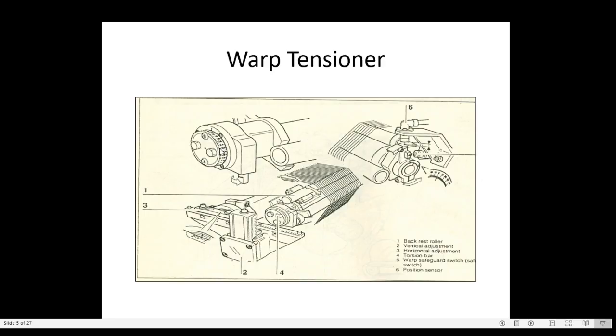When 5 kilonewton comes, we fix this nut. First we loosen this check nut, adjust to 5 kilonewton, and after it comes, we tighten these lock nuts. So these are the whip roller settings. One is the vertical or horizontal setting. Next is the torsion bar setting, or backrest spring setting as it is called. Here the spring is not there, the bar is there. So this is on one side of the machine.